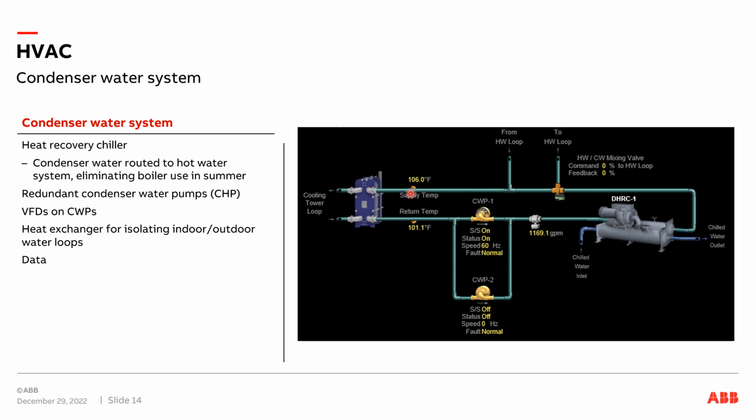The most common one is that it's going to go straight to a cooling tower, and we'll get to the cooling tower in a little bit. But what we do is use what's called a heat recovery system with our chiller. Remember when I said that you have those VAV boxes and you have to warm the air back up sometimes if somebody in an office likes it warm in there? It seems really wasteful to spend electricity and energy to cool the water, cool the air, and then spend more energy to warm it back up just for a specific office.